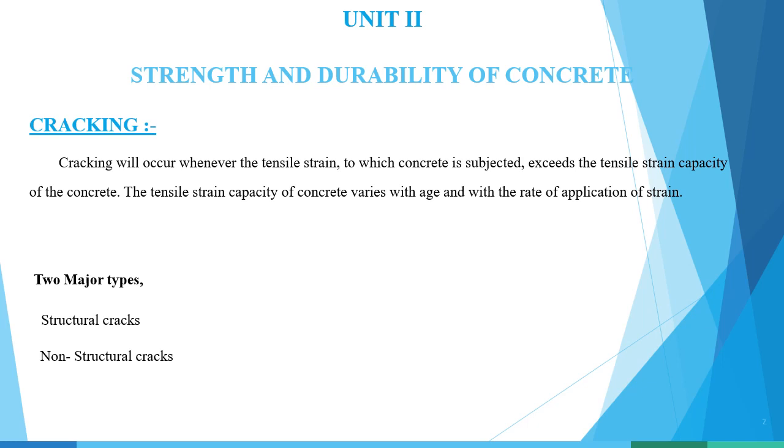Cracks develop when the stresses exceed the cracking strength in the structure. These are likely to spoil the internal finish of a building due to the penetration of moisture and thus increase the cost of maintenance. Cracks due to different causes have varying characteristics. It is only by careful observation of the characteristics that one can diagnose the causes of cracking and adopt the remedial treatment.